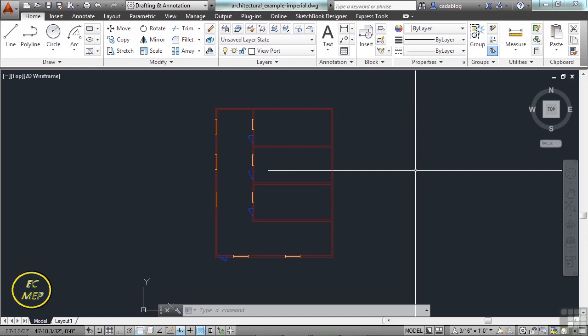Most of the hiding thing has to do with 3D objects. You can have hidden lines, you can hide things behind them when you look at certain isometric views, such as that. So in a 2D drawing, the hide part doesn't really come into a lot of play, especially in AutoCAD LT. But in large drawings, freezing unneeded layers speeds up operations involving displaying them and regenerating your drawing. Thawing one or more layers can cause the drawing to be regenerated. Freezing and thawing layers will also take more time than turning layers on and off.